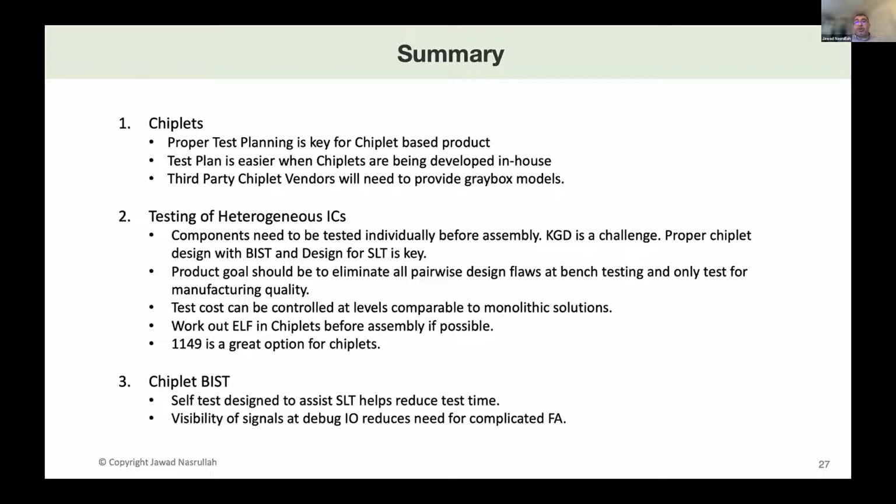The other strange problem with these interposers, which is prevalent in 3D and in high bandwidth memory, is that the moment you put a lot of parallel wires or connections and you turn on switching, there are inductive kicks, and the power delivery network can be pretty stressed out.